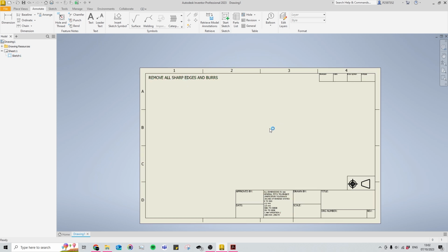Now's the time to make any changes you would like, as we're about to save it as a blank template you can open every time you go to dimension a drawing. So now your border is created and filled with the info that suits you, you can finish the sketch and then name the border. The border won't show straight away. To add the border, open the border folder in the model tree and double click the border we just made.